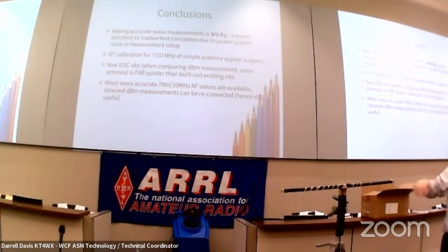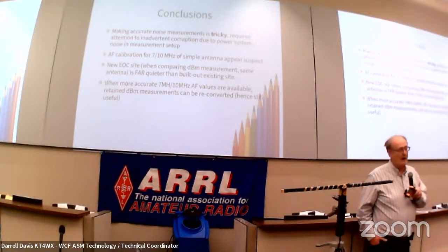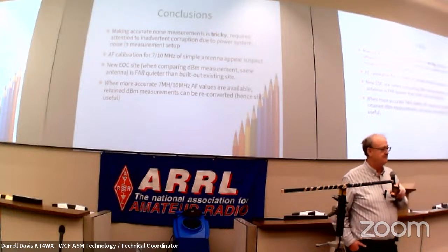And the second noise generator is the inverter. And its noise is on the output side, and it goes to your house and uses your house wiring as the antenna. So I'm caught between two antennas. My solar panels are the first antenna, and my house wiring is the second antenna, and they're both trying to destroy my 20-meter DX. So I just got to turn the thing off. But eventually, I will put in some of these fancy filters, maybe after the warranty runs out. And it'll probably quiet down dramatically after I do that.